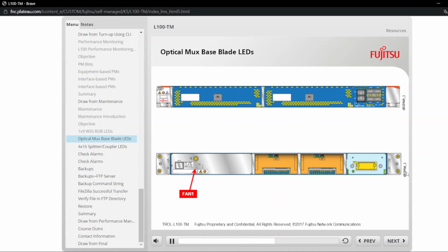Fan 1 and Fan 2 LEDs, for fans. Off: no power. Green: normal operation. Red: equipment fault, a fan failed or was removed. Blinking red: fan mismatch. Loss of LED activity may indicate that the PIU is in reinitialization mode, operator activity, and not necessarily out of service, OOS.